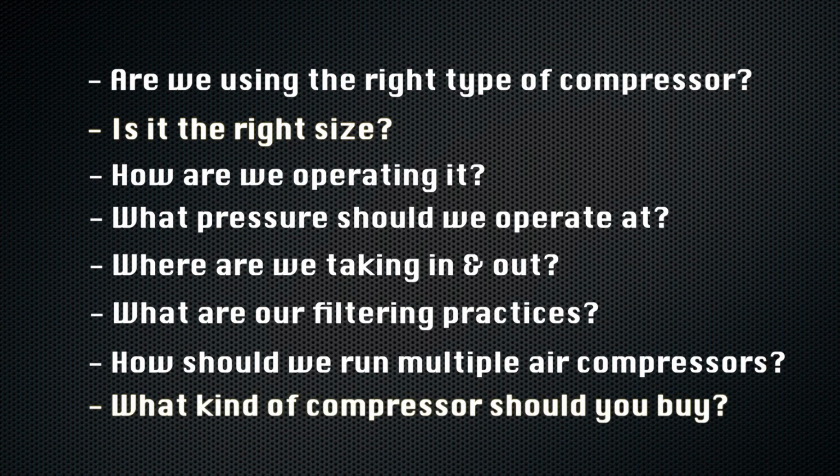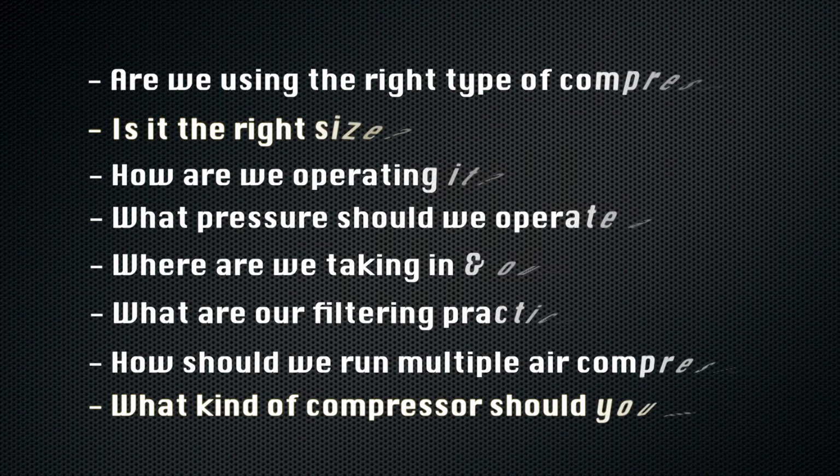And if you were going to buy another air compressor because you're expanding or whatever, which one do you buy and what does it look like? I like to start by looking at the load profile for my compressed air system. Easiest way is to monitor the kilowatt draw from the power panel into the compressors. But this normally requires shutting down the system to hook things up.